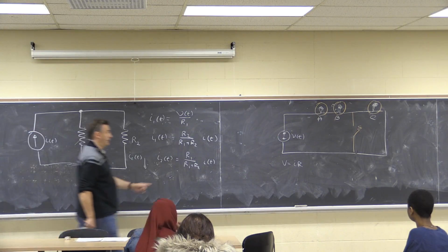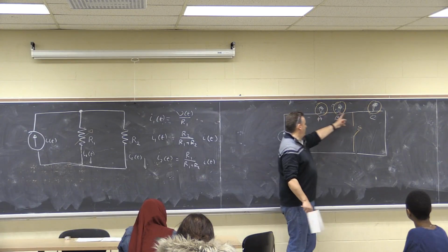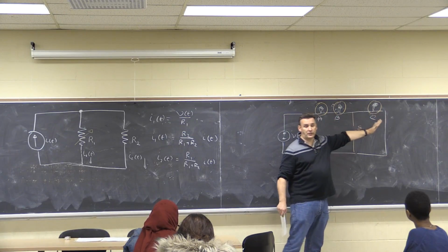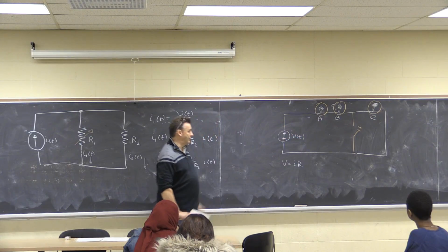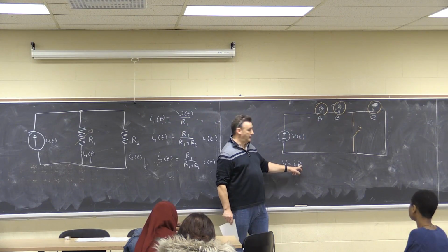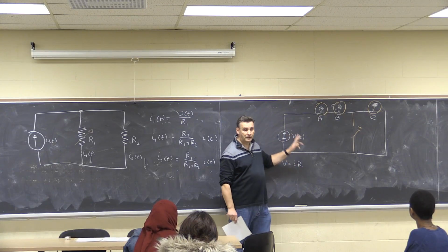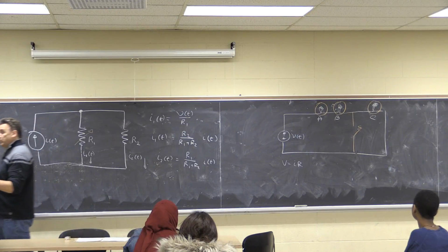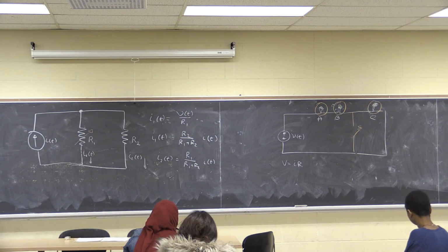The circuit I'm interested in now is through A, B, and through this route here, because this is a short circuit. If there's a short circuit, it doesn't matter what's across here, none of the electrons get into that side. So the resistance goes down, current goes up, so the power dissipated, V times I, goes up. So lights get brighter. So one goes off and two get brighter.